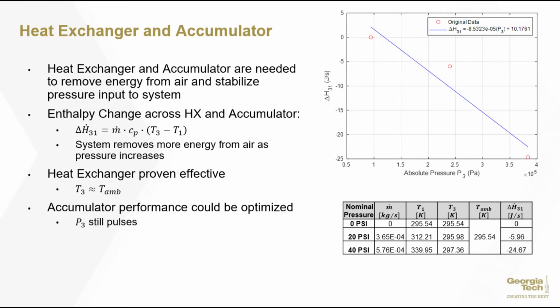However, from previous graphs, it's clear that the pressure at station 3 is still pulsing slightly, so the accumulator could use some improvement.